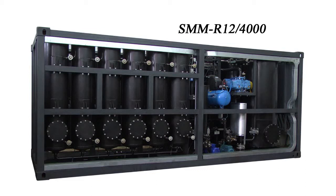At this time, energy facilities have an increasing number of power transformers in very poor condition. The main cause of transformer failure is the decrease of polymerization of solid coil insulation due to the effect of acids which form when transformer oil ages.